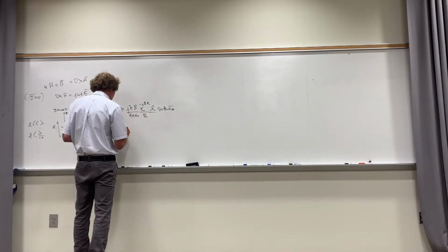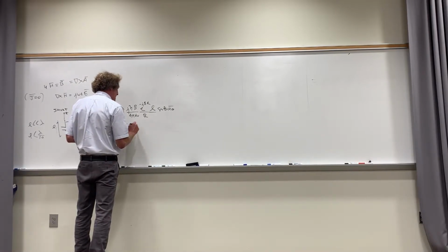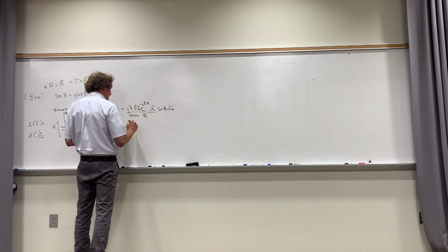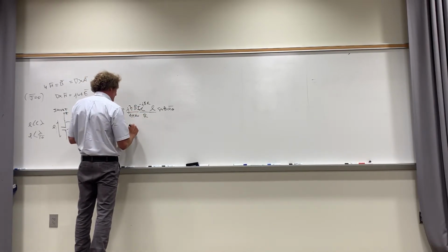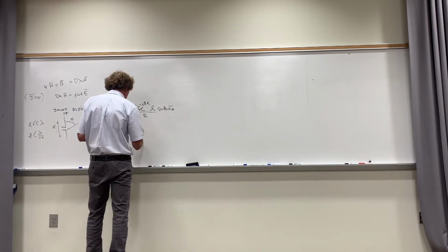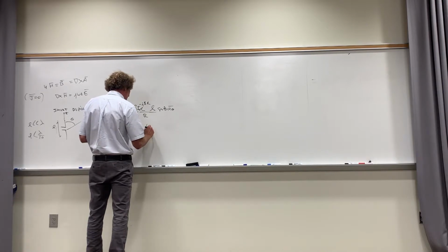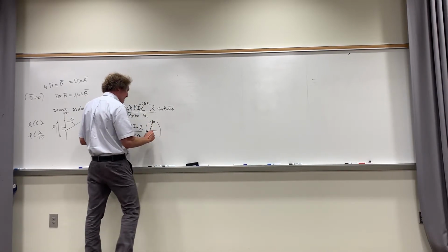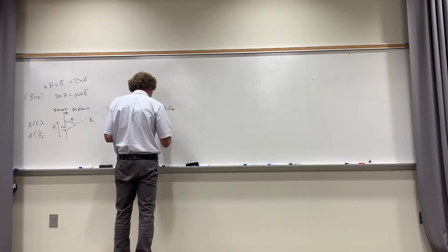So it's going to have the same form, j beta. Oh, by the way, somebody should scold me here. I didn't put the current value in there, I naught. j beta I naught over 4 pi epsilon naught times L times the quantity e to the minus j beta r over r times sine of theta, a theta.